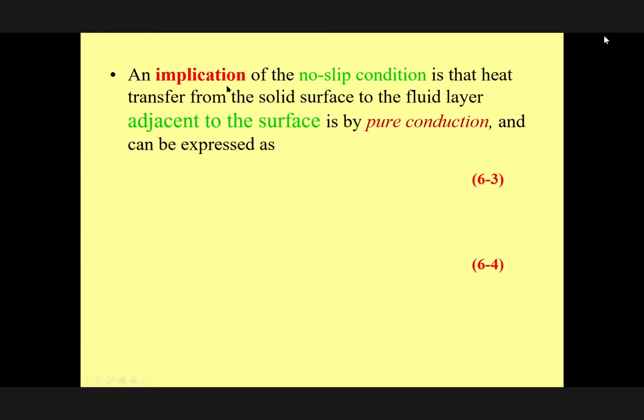Again, as I mentioned, there is heat transfer from the solid. Here, just on the surface, it is pure conduction. This is from the lecture that we had. I show it here to you because that's one of the assumptions we made. We assume the convective heat transfer from the surface to the bulk of the fluid, T infinity, from T surface to infinity, is the same as heat transfer by conduction through the boundary layer, not through the solid. I'm talking about the boundary layer, and that's what we define here.